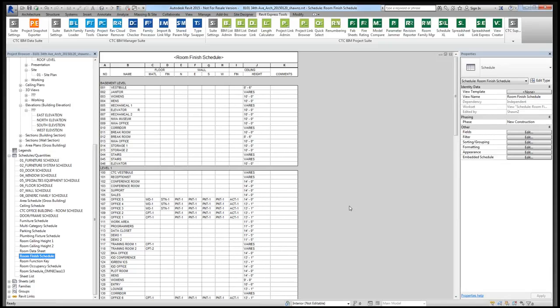There was a comment that said it would be nice if somehow within Revit directly I could bind a room and ceiling schedule together. Obviously, the room itself is somehow tied to the ceiling. It's being bound by it. And I looked at that, man. I really tried. I wanted to find out what the individual bounding objects were. Unfortunately, Spreadsheet Link doesn't have the ability to show that to you. I really wanted to use that as my method. But there's no way of very easily, at least within Spreadsheet Link, finding that information out.